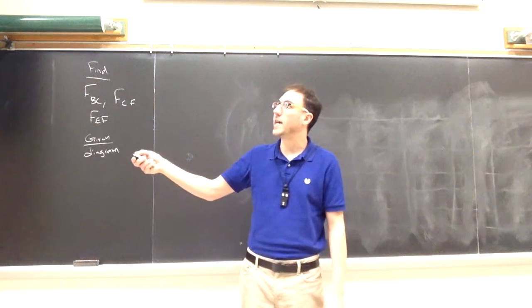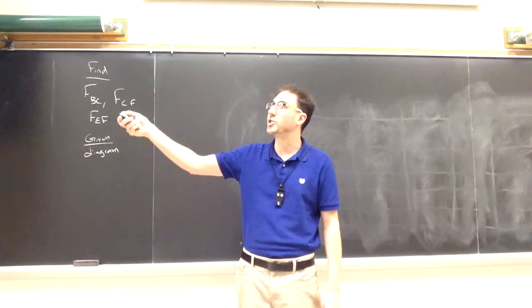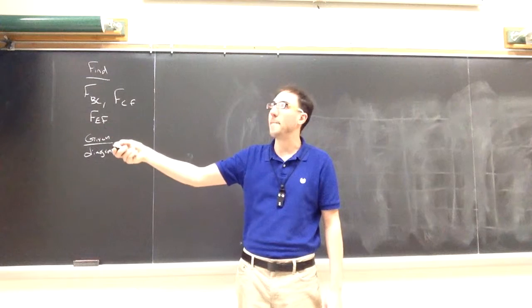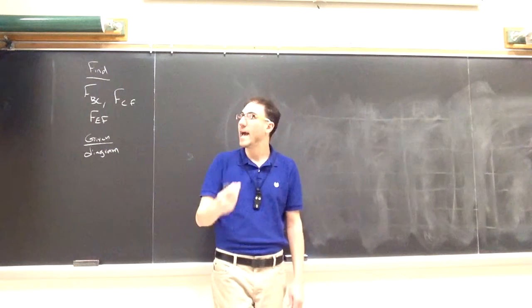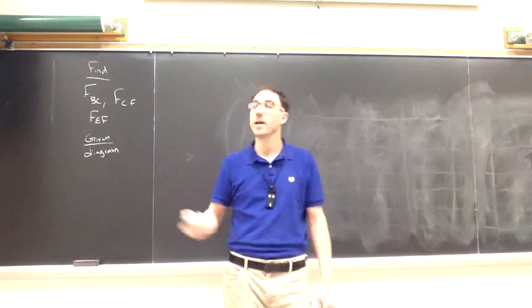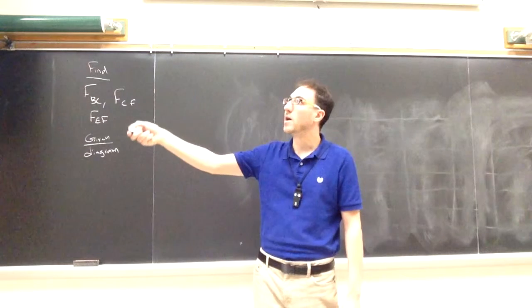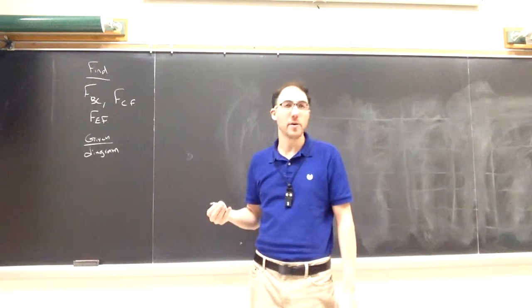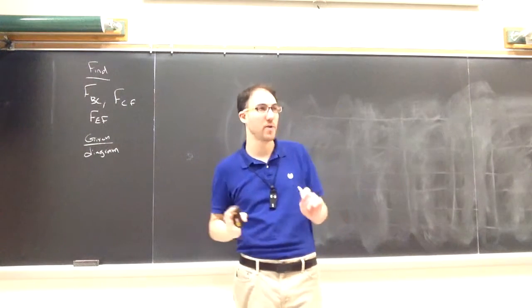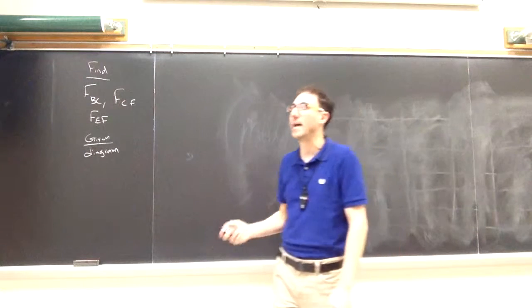So here, if I take everything to the left of this cut, I will be including G and A in that picture, meaning I would need to include what is AX, AY, GX, and GY, as well as the force in all of the members that I'm cutting through. So if I made this cut without an external free body diagram, I'm going to be introducing 7 unknowns right away in one picture. And I won't have enough equations to cover that.